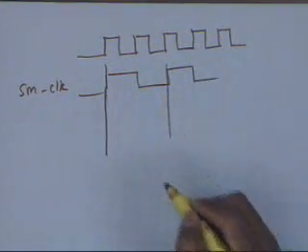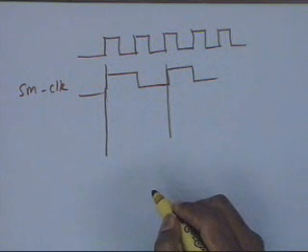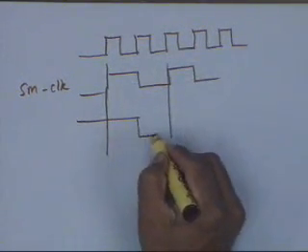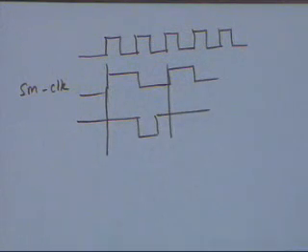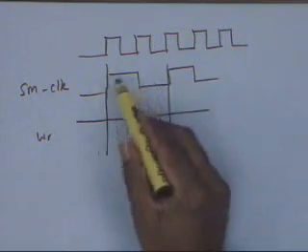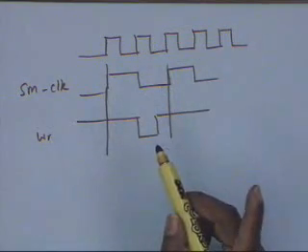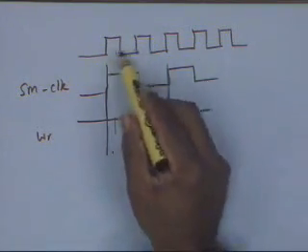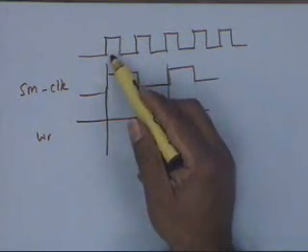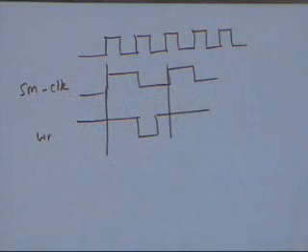You are going to perform your write operation in one clock cycle of the machine cycle, and now it is fairly easy, by gating, to generate a pulse like this, which is the write pulse that you use. As far as this clock is concerned, you are doing it in one clock cycle, but this is the clock which is the source from which you generate the state machine clock. So in relation to that, you are taking 2 clock cycles to do the write.